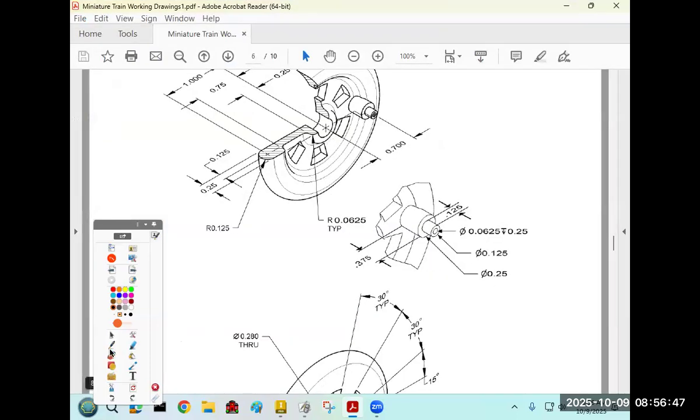Okay, so let's see what we've got. We've got this nub that sticks out. This widest part has a diameter of 0.25 and is extruded out 0.375. Then there's this next part that is 0.125 extruded 0.125. And then there's a hole that's this big and 0.25 deep. They're all centered on top of each other, which is easy. But the key is we have to know where to draw this first one, and this first one is 0.7 from the center.